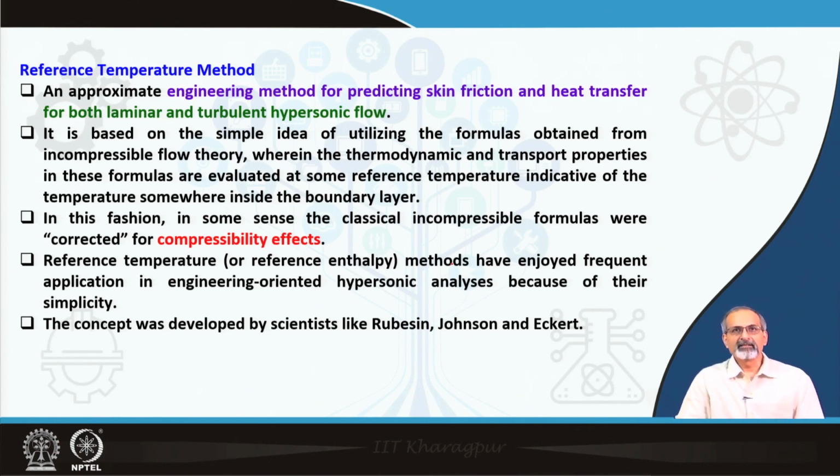So, this is a very handy tool, which without explicitly solving the ODEs which give us the solution of the compressible boundary layer equations, we can still generate fairly good estimates of skin friction and heat transfer, both in the laminar as well as turbulent boundary layer cases for hypersonic flow.